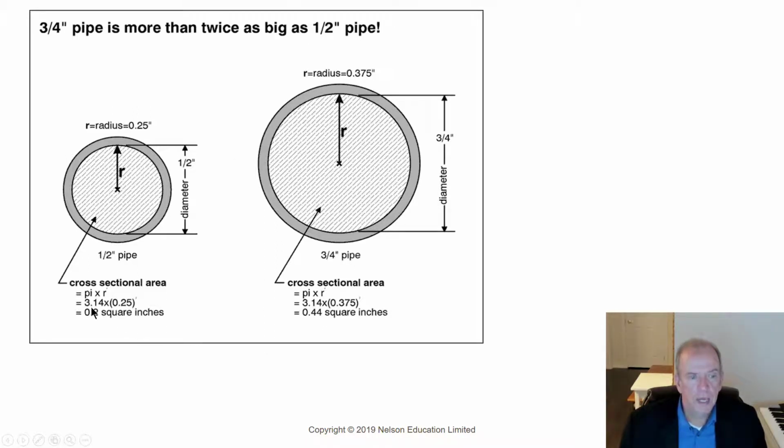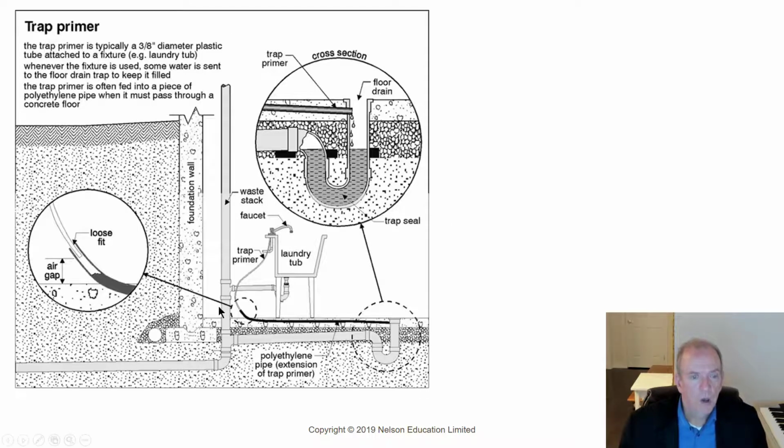So you can look at that, and that kind of tells you the difference between a half-inch water supply. Older houses, like 30, 40 years or more older, only have a half-inch supply from the street. So they will not have the same kind of pressure that more recent houses will have. And that's why when somebody turns the shower on in one room, in the other room, you're in the shower and you're freezing.